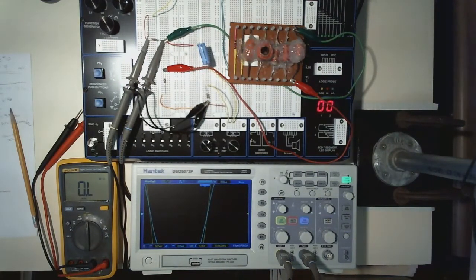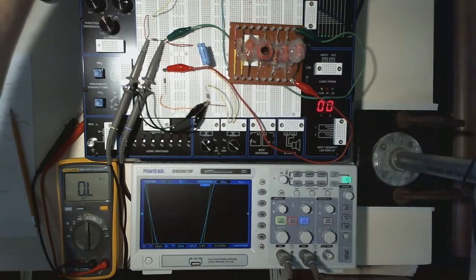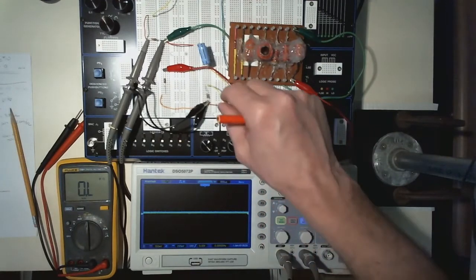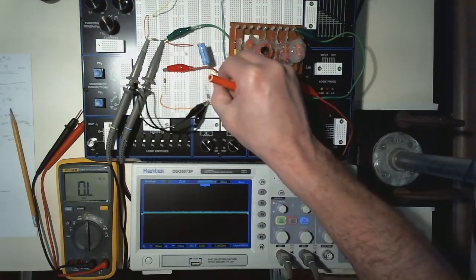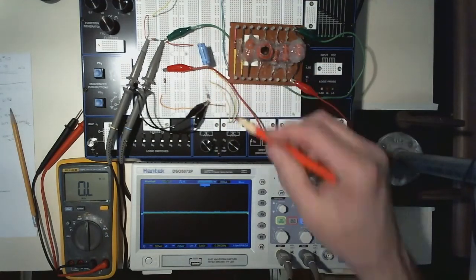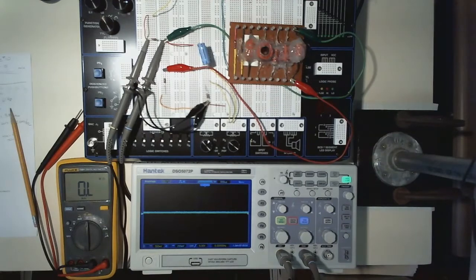So now what I need to do is measure this resistance here. I'll go ahead and turn that off, and then I'm going to pull this wire out so that I can measure across the potentiometer. You have to unhook one leg of the potentiometer to do that. And this is where I want you to do those pre-calculations.